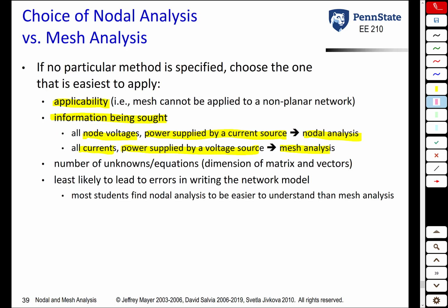The biggest thing you want to look at, though, ultimately is the number of equations you need. You'll see in an example in a minute that the number of equations might vary from nodal analysis to mesh analysis. So if one method requires fewer equations, it might be the one to use. Finally, there's a reality that some people find nodal analysis easier to understand and some people find mesh analysis easier to understand.